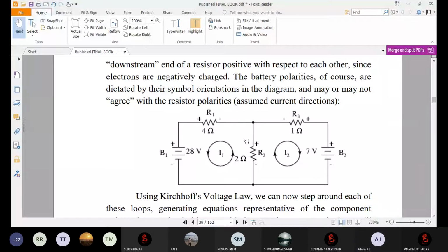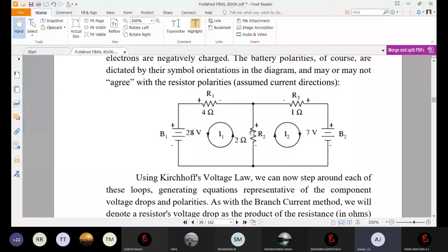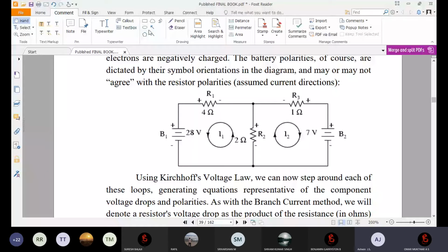Okay. We have two resistors. We have to consider the resistors. We have R1, we have R3, as well as R2. So in R2, both the currents flow. So this is nothing but I1 plus I2, right? Guys? Yes sir. In R2 we have to put I1 plus I2. Here actually, in that circuit it is represented as I3. So I3 is nothing but I1 plus I2.